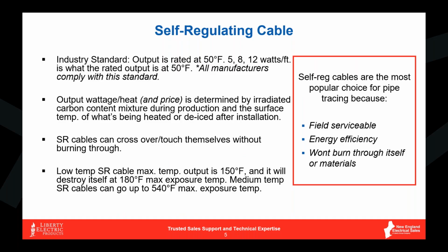Now, the colder you get from 50 degrees F, the more heat this cable is going to deliver. Conversely, as you heat this cable up, it does not want to deliver as much wattage. So that's how it kind of gets its self-regulating name. So low temp self-regulating cable is generally what you're seeing for about 95%, 99% of the market.